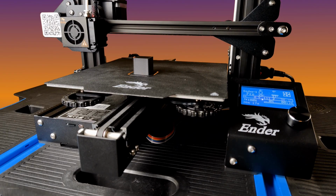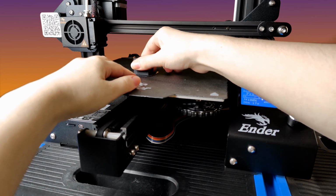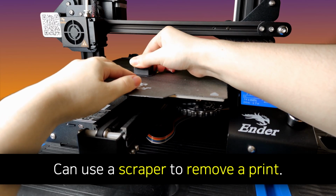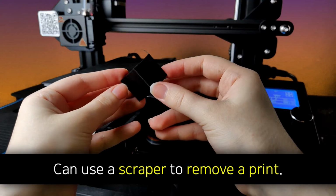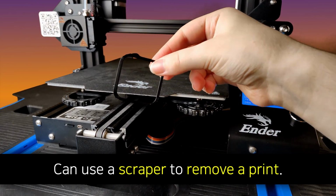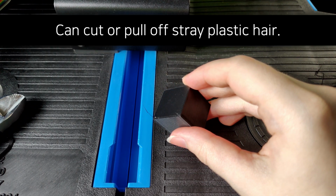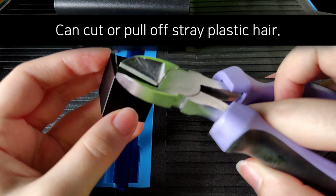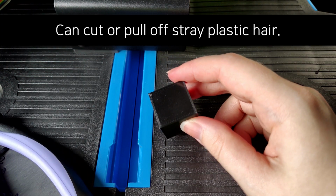When the printer is finished, we can remove our cube and the skirts from the printer's bed. If there is a struggle to remove what we printed off of the bed, then we can try using a scraper of some sort to get it off. For this, I prefer to use a plastic scraper if possible. If there is a stray plastic-like hair where the printer finished, we can cut that off by using scissors, wire cutters, or we can even just pull it off with our fingers.